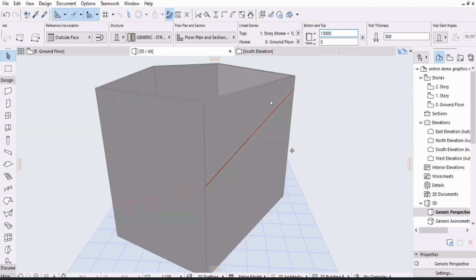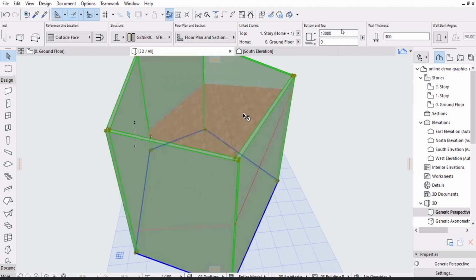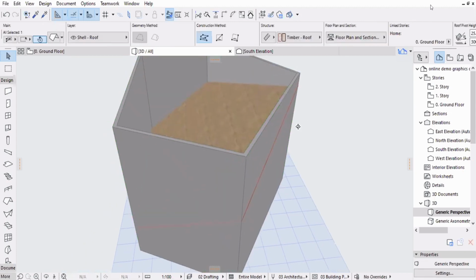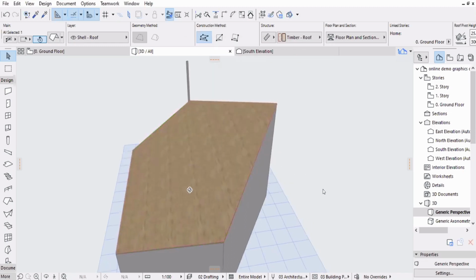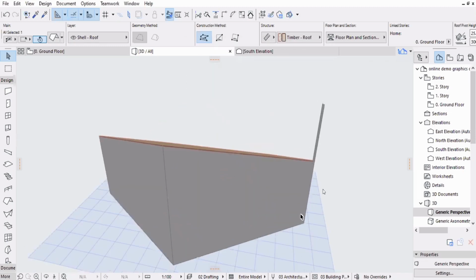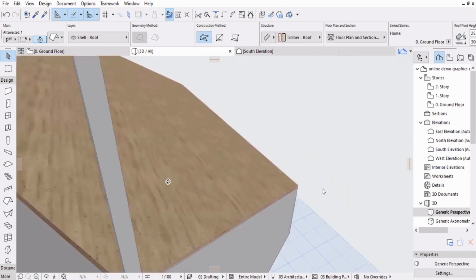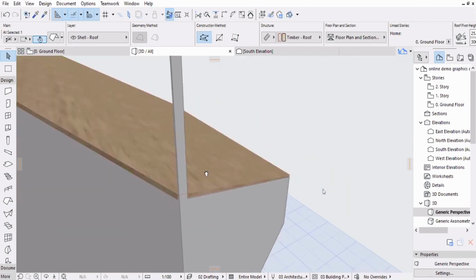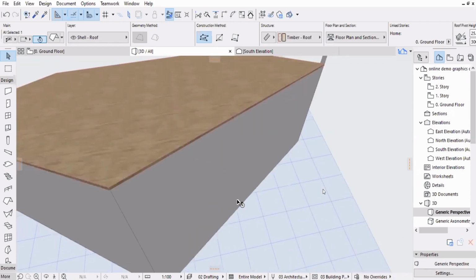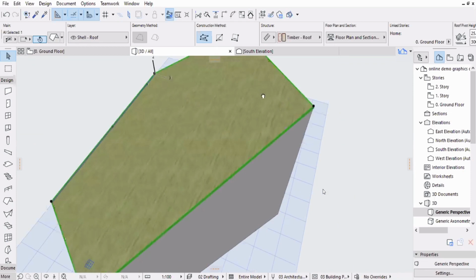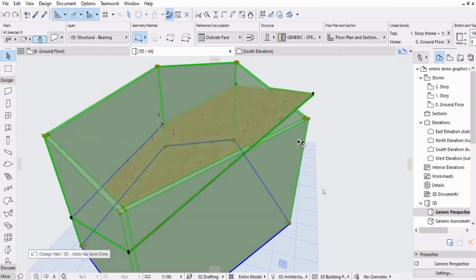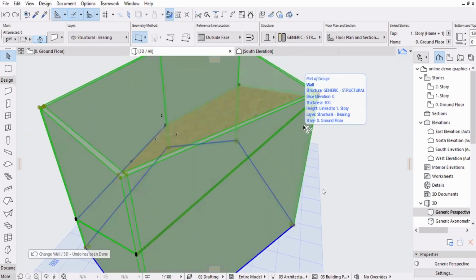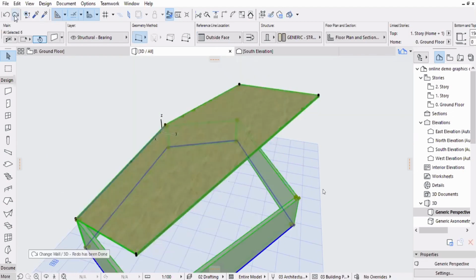Yeah. So now if I try doing the trim, the trimming involves a very simple step. Just select the roof, right click and say crop to single plane roof. When you say crop, it works. Sometimes it works, sometimes it doesn't. But it'll always give you some issues like this, like the corner is not trimmed because of some issues here. Sometimes it may be cleanly cut, sometimes you might have issues like this. So the best and safe way to do things is basically, let me, one second, I'm undoing, I should redo things.